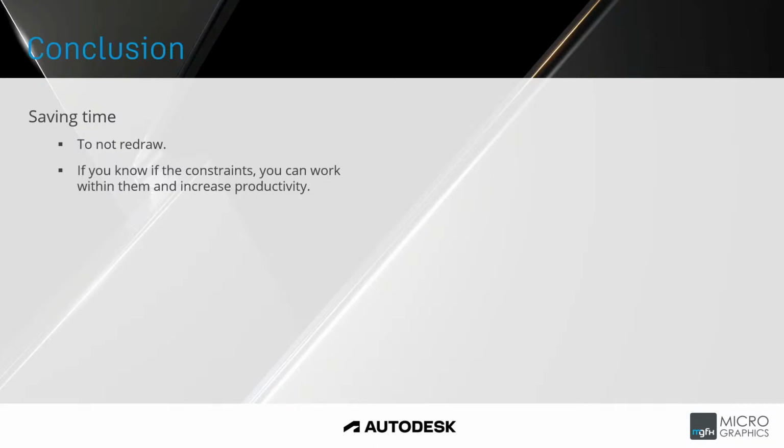So in conclusion, I think if you know the constraints that you work within, it will save you a lot of time, because you don't have to redraw, etc. And again, try to use option 2, meaning open up a furniture family, insert it in there, set up the family, make sure the materials, etc. are right, and then bring it into Revit.